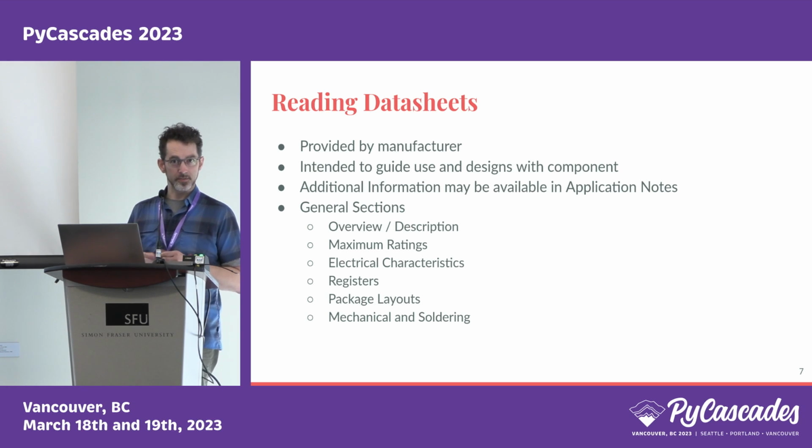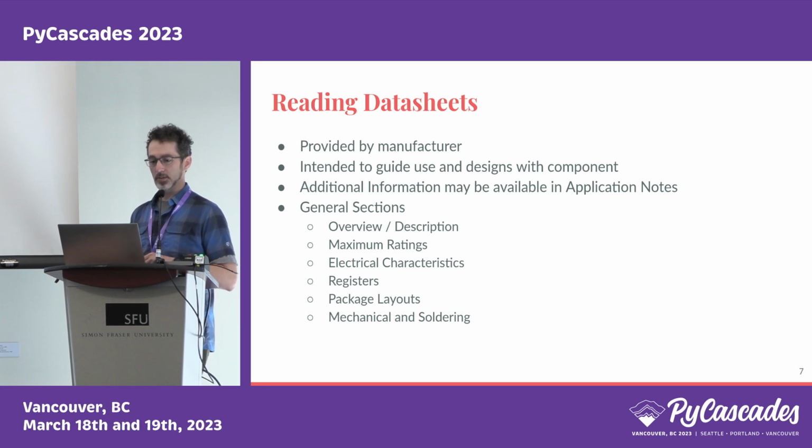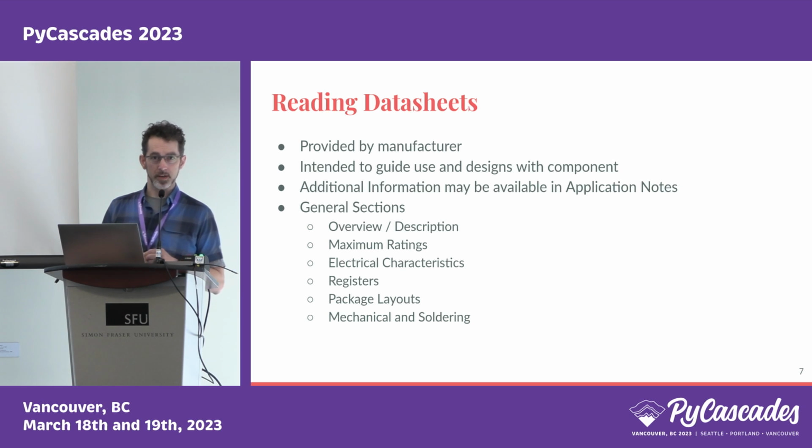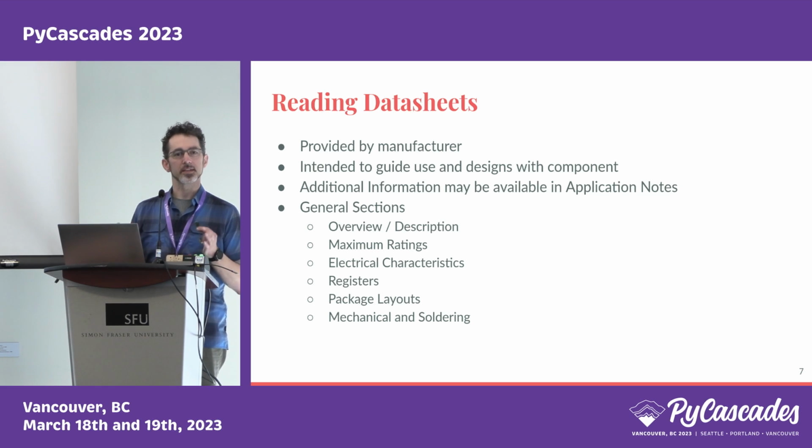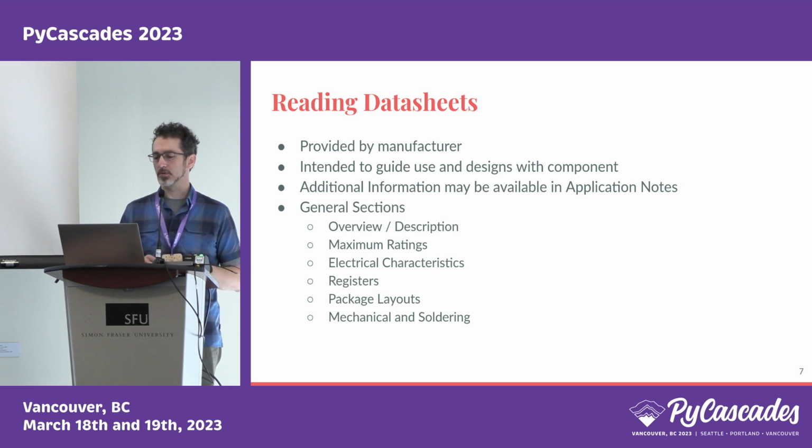So, having selected our device, the next thing to do, and I should point out, I looked at the data sheets for all of those, and that was another differentiator, as I wanted to find one I could actually understand. So, we will spend a bunch of time in the data sheet in this talk. Data sheets are something provided by every manufacturer, and they're intended to guide the manufacturing and the programming and the integration of that chip into your design. It'll include a lot of things that we'll use, but they also include things like what's the maximum temperature that it can handle, how much voltage or current can it handle, what registers exist, and how big it is, how you'd fit it into a package on the rest of your board design.